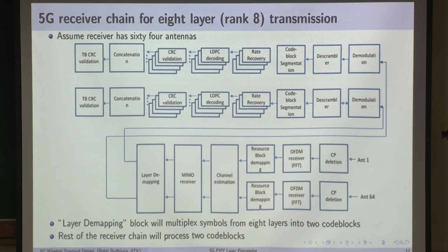2 instances of receiver chains means what? Just for example, 2 different LDPC decoders. So whether your device has the space to occupy 2 LDPC decoders or not. If you pick a device which can run at a higher clock rate, but does not give you the memory wherein 2 LDPC decoders can fit. So these are the design decisions you have to take in the beginning. Typically, when you architect a system, you look at all this and then design your system.